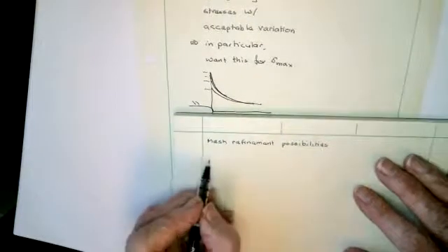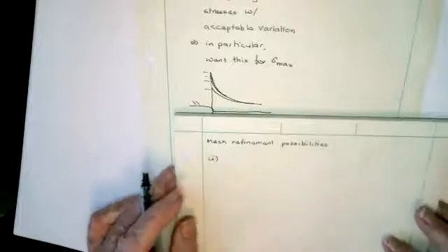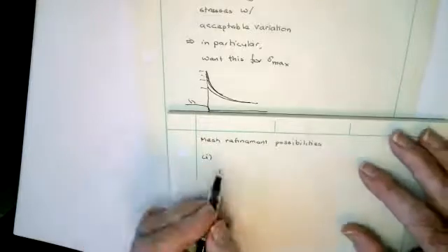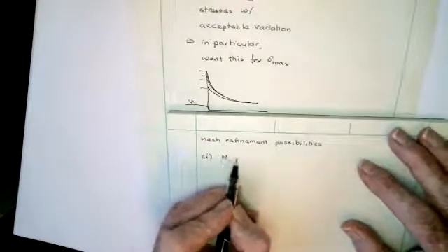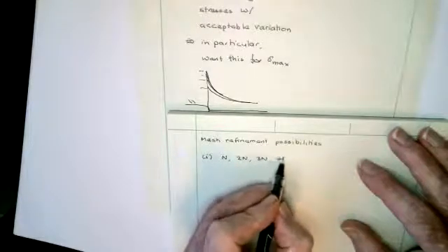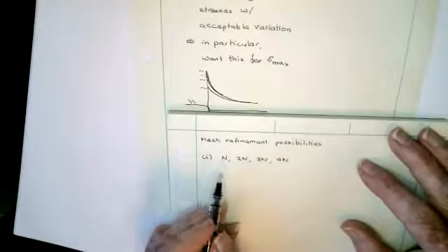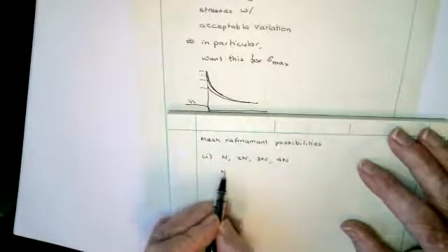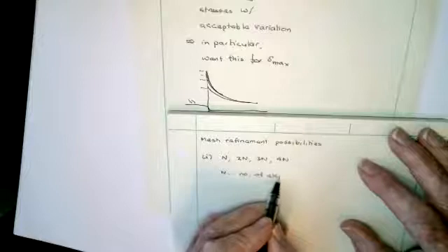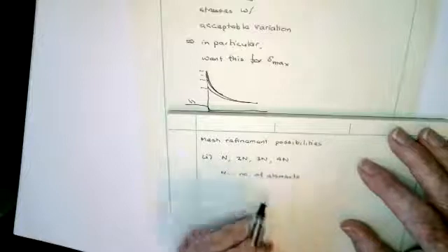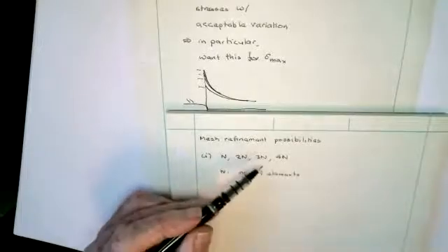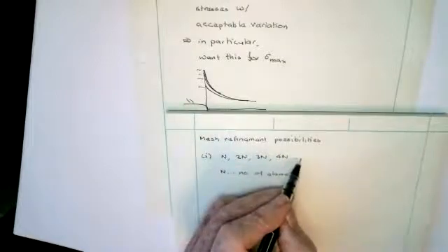There are two schemes that are practiced for mesh refinement with finite element analysis. The first is a sequence of meshes with N elements. The first mesh might have 100,000 elements, then 200,000, 300,000, 400,000, and you see if your answers are converging.